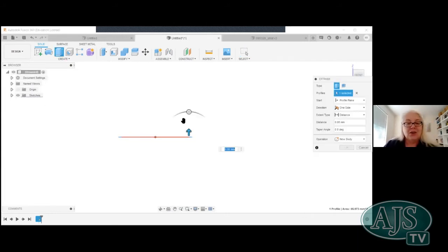And now I'm going to extrude it. So clicking on this little block here, we get a whole new set, and I can just pull that up. Let's say I want it to be a 4mm wide band. So I can just pull that up there.